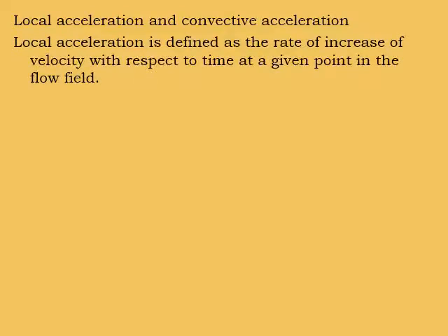Next, two terms connected to acceleration, that is local acceleration as well as convective acceleration. Local acceleration is defined as the rate of increase of velocity with respect to time at a given point in the flow field. So here one particular point is considered in a flow field, and with respect to time, the change in velocity or increase in velocity is measured. So that is called local acceleration.